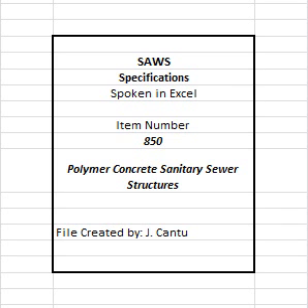2. Materials paid on site will be in accordance with Table 1 of Specification Item Number 100, Mobilization. 3. Concrete cradles for pipes shall be measured and paid for at the contract unit price bid as provided for in Specification Item Number 858, concrete encasement, cradles, saddles and collars. 4. Gravel subgrade filler for structures shall not be measured separately for payment.